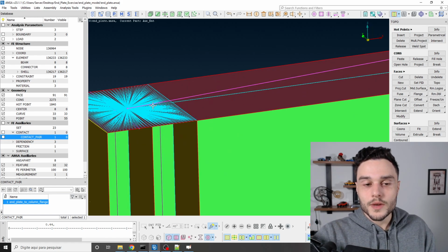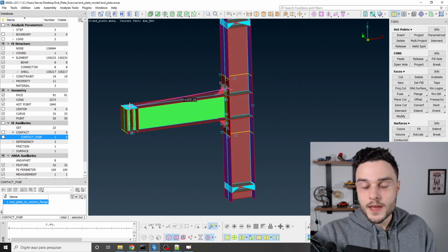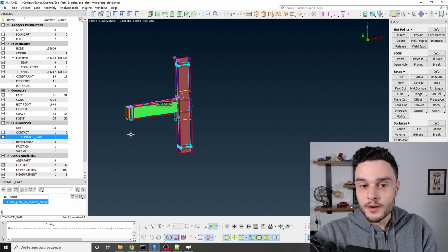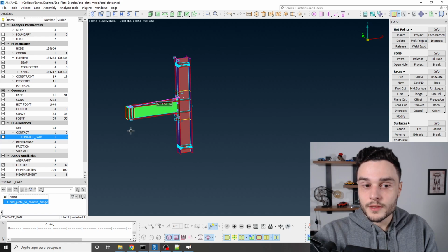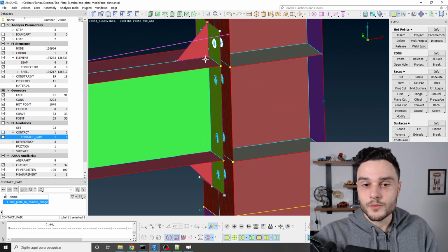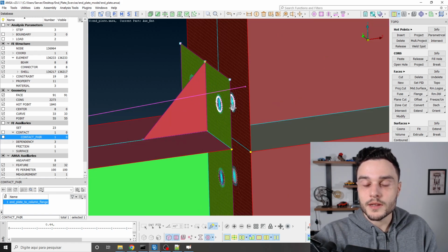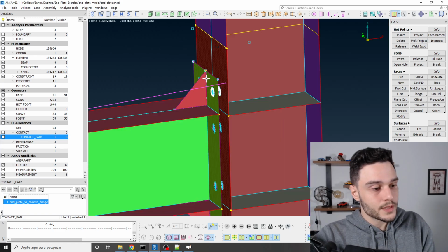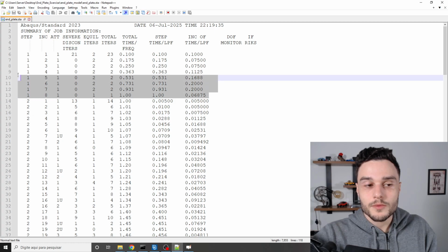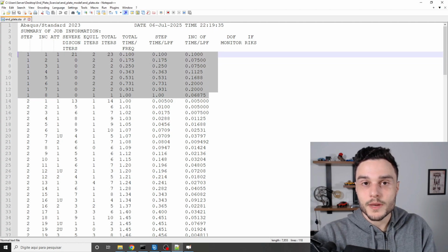So while we have, for example, this displacement occurring, the stiffness of this whole structure is going to change because this is a nonlinear analysis, because we have material nonlinearity due to plasticity, we have large displacements and large deformations, nonlinearity, and we also have contact nonlinearity. We have a contact here with friction that allows sliding and also separation.